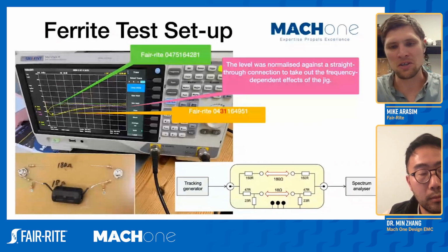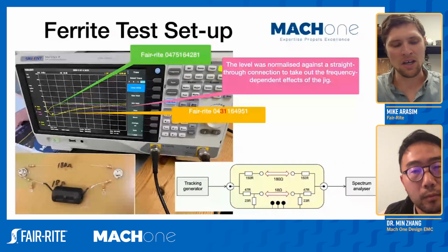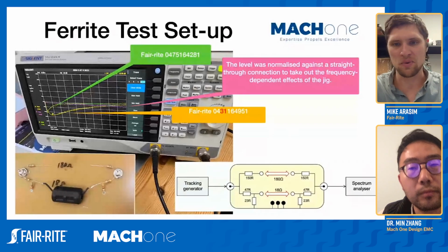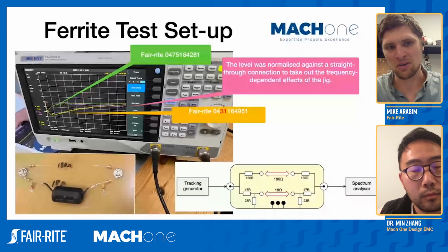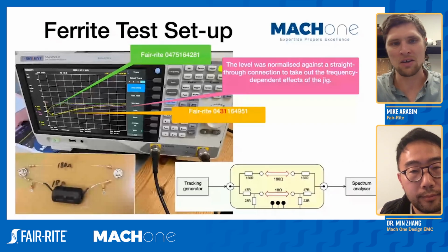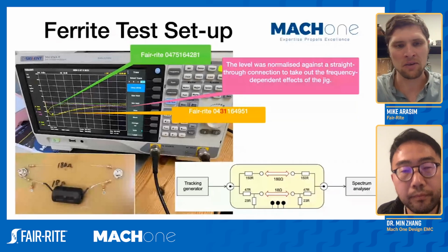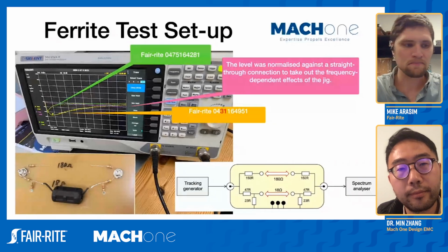We have some of the test methodology outlined on our website. They're fairly basic loop-to-loop coils with the sheet in between or perpendicular to, depending on the test method. We look at reflected and emitted coefficients, S parameters, to calculate that. But that's pretty much what we do internally.